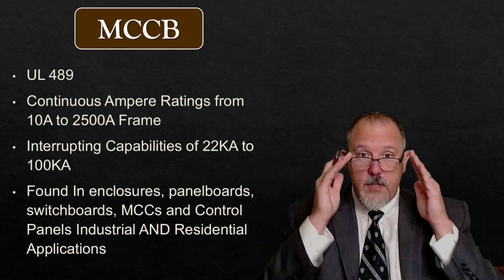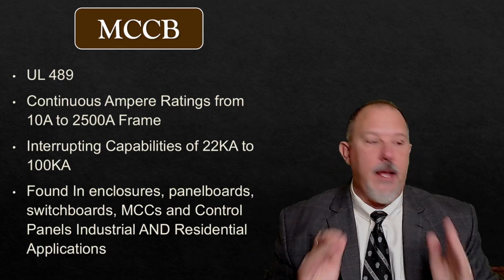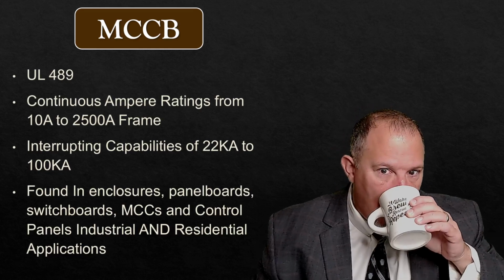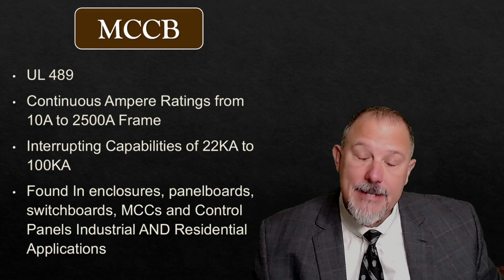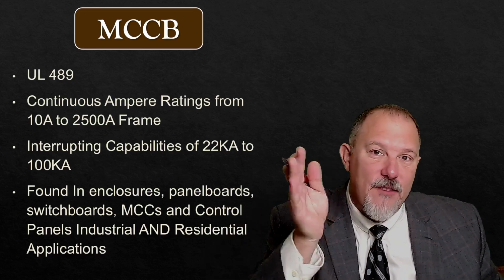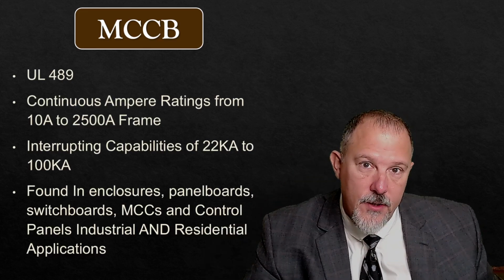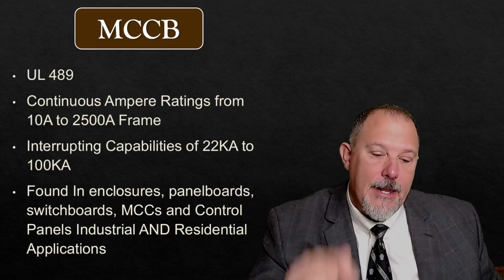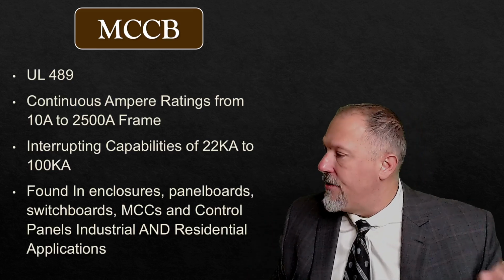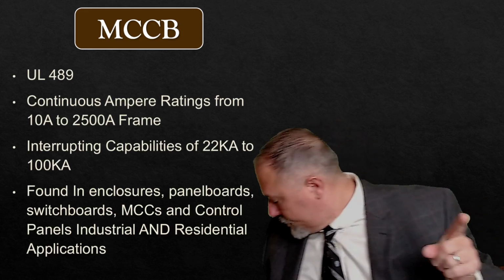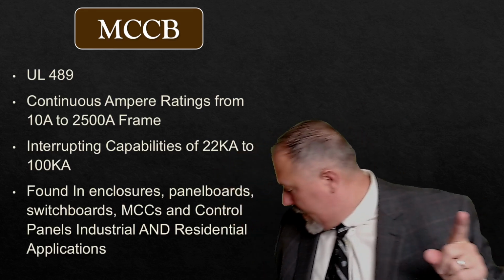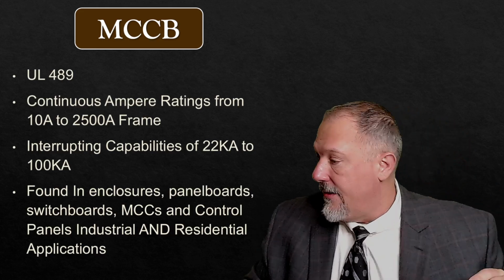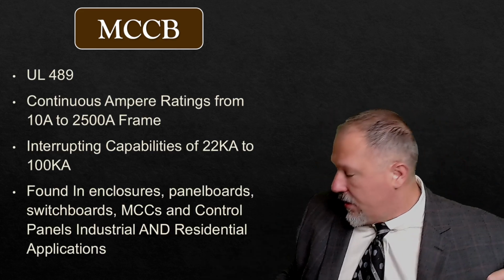What else? Oh, a molded case circuit breaker. You know how you can tell a molded case circuit breaker from any other circuit breaker out there? It has a handle on the front that goes up and down or left and right. You're going to physically push something up and down to turn it on and off. And why is that important to understand? It is important to understand that little detail.